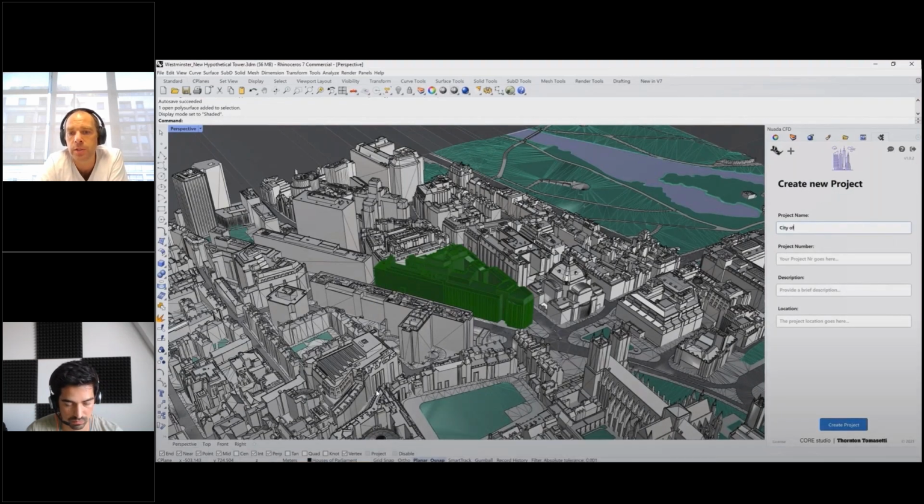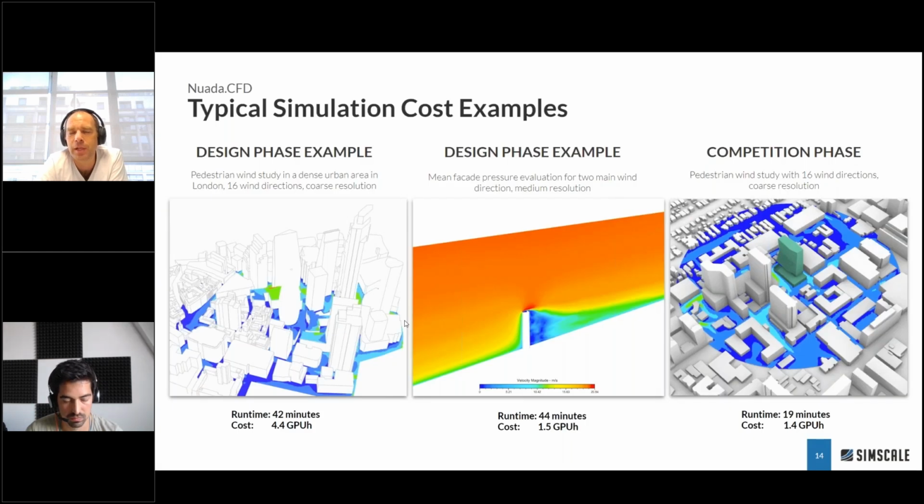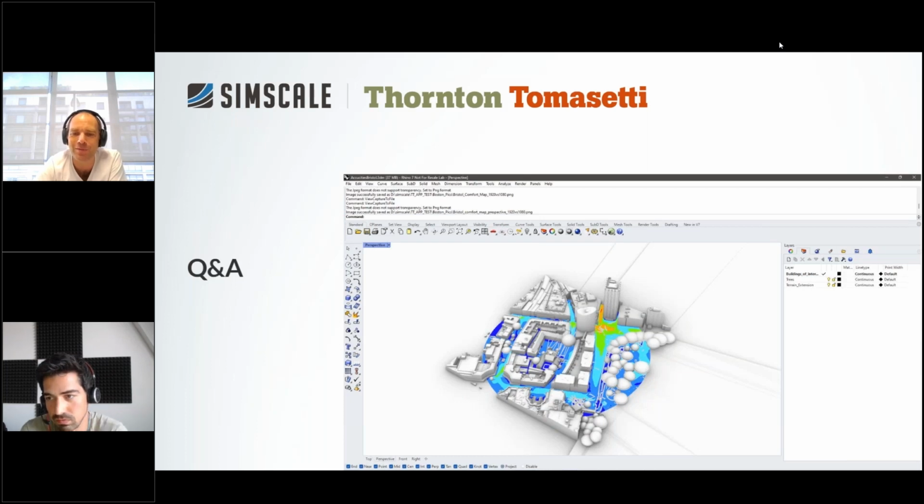So if you go very coarse, what I've seen is often it looks windier, and when you go more fine of a resolution, but therefore also more time consuming and more costly, the comfort values actually go down, but don't pin me on that, right? But that's what I've seen so far. But with those higher resolution simulations, you will also see a better difference between if you do stick in a balcony, a balustrade, or a parapet, or some trees, because specifically the trees.